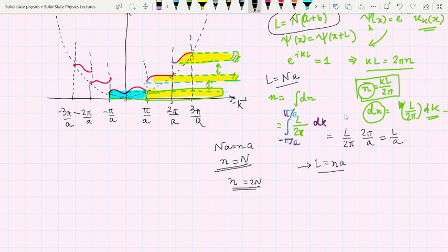Now, the allowed electronic energy states fall into bands which are separated by regions known as forbidden energy gaps. The number of available states in the band depends upon the number of atoms present, and due to the spin plus minus half of the electron, the total number is 2N. That is, 2N electrons will be required to fill the first band.